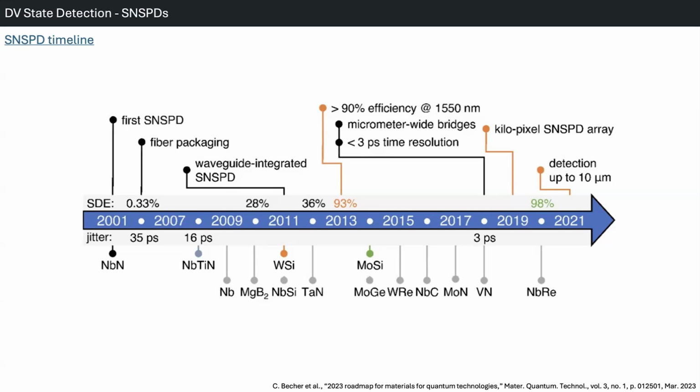What do we have as alternatives also? I won't mention them all, but you have InGaAs, indium gallium arsenide technology. Germanium has recently become a trend as a research topic, but they produce very high dark counts. Let me talk a little bit about the dark counts.